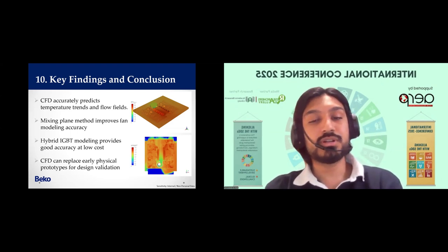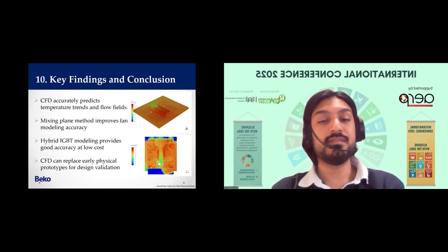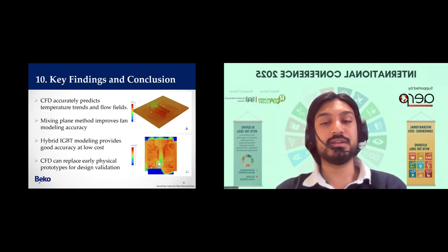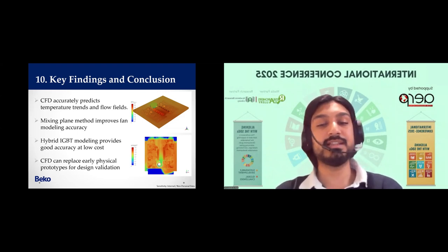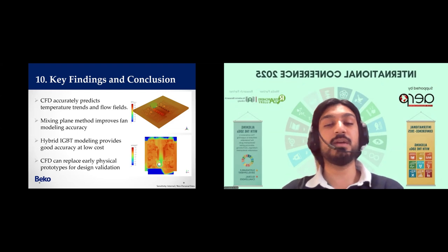In conclusion, our CFD model achieved about 80% agreement with the experimental data, validating its feasibility for design use. For future work on this kind of cooling design simulations, we plan to perform transient analysis, taking into account the power reduction software involved with these kinds of products. And we will also explore alternative fan and heatsink designs to ensure cooling performance and reduce the noise. This modeling approach can ultimately contribute to quieter and more efficient and reliable induction hobs.